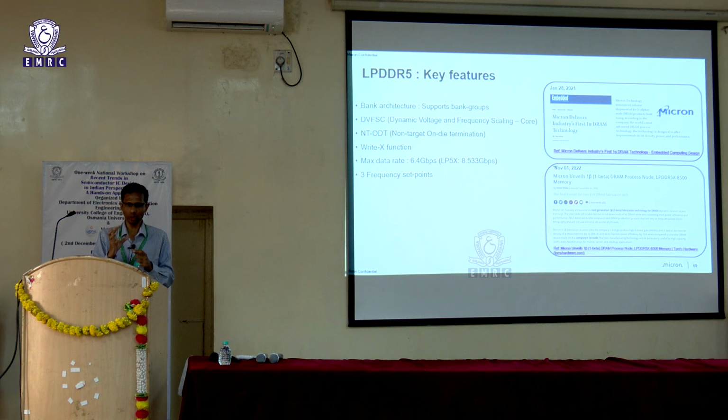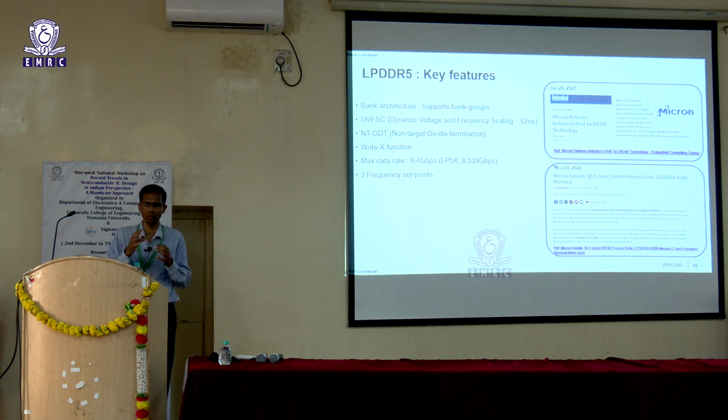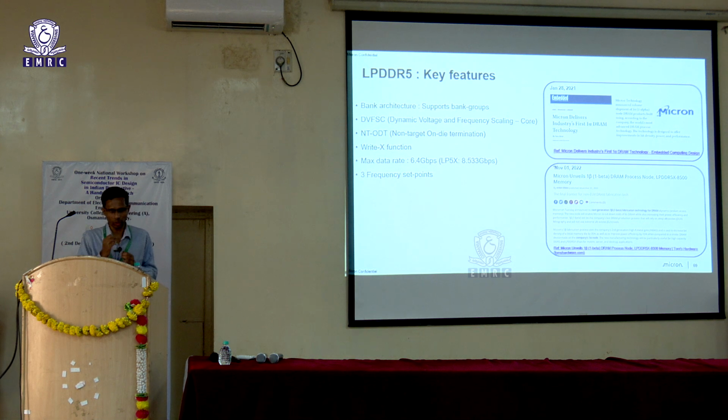and then this bank group versus the next bank group, if you are doing an access, you will have a different timing versus accessing all of them simultaneously. So that way you are able to improve on the speed here. The other feature that was brought in is called dynamic voltage and frequency scaling. Probably if you have gone through a digital design course, you would have come across this term, dynamic voltage and frequency scaling.